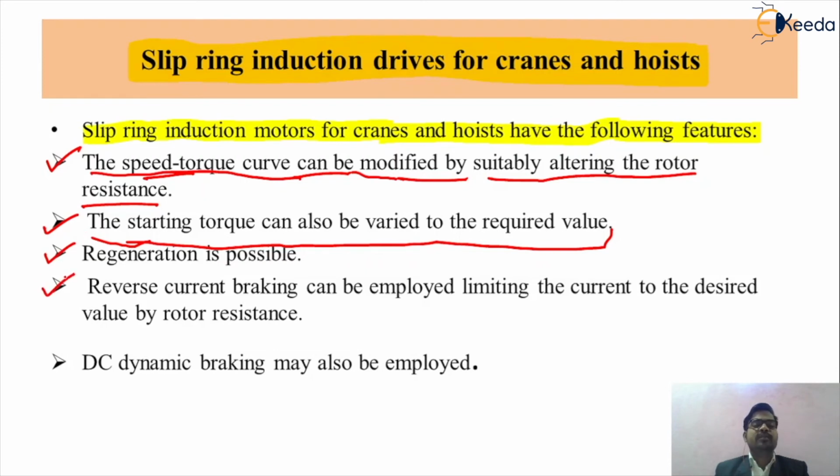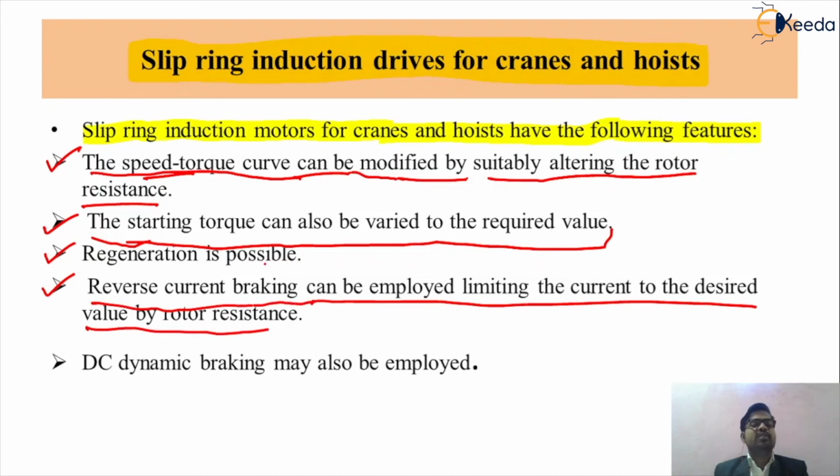Then the next feature is reverse current braking, which can be employed by limiting the current to the desired value by rotor resistance. So friends, obviously while we are using the rotor resistance control technique in the slip ring induction motor, we are getting various important features. So reverse current braking is also possible in a slip ring induction motor.